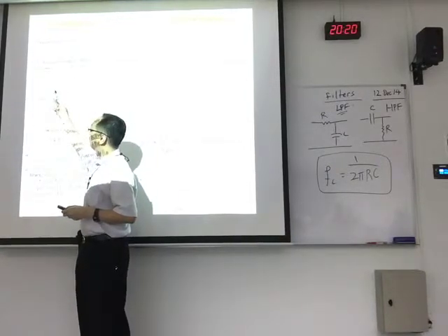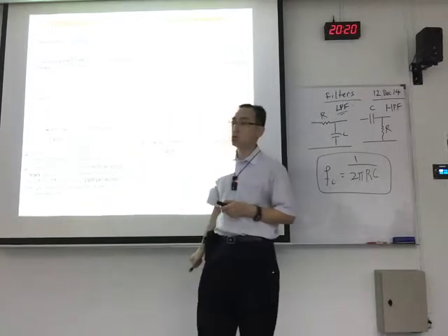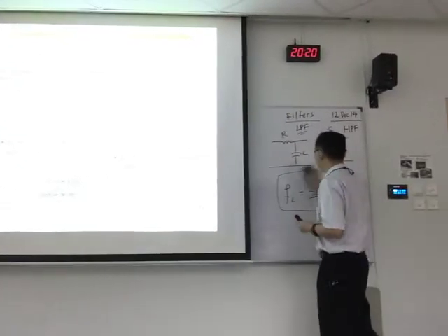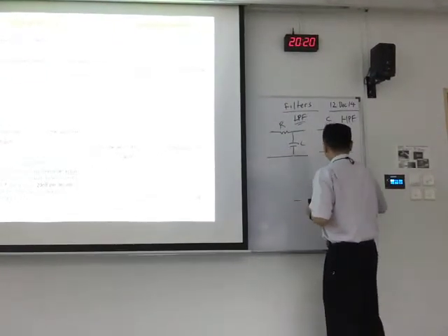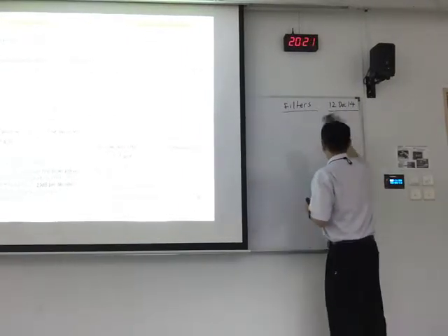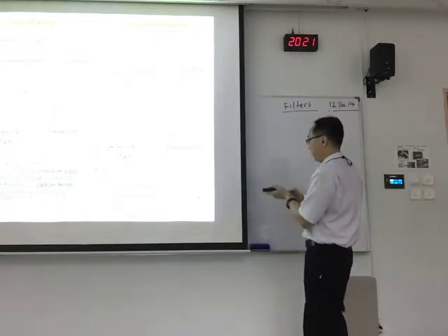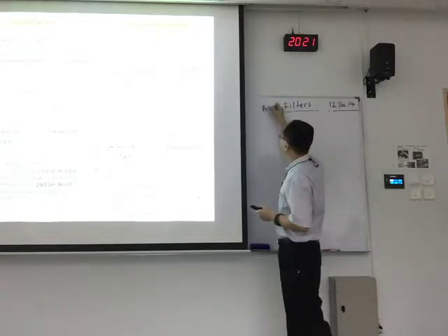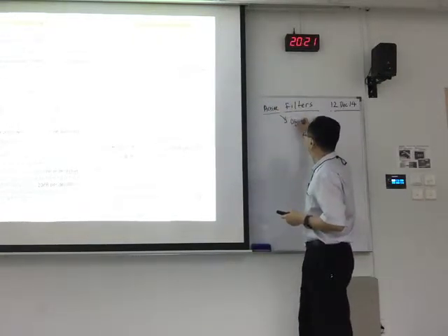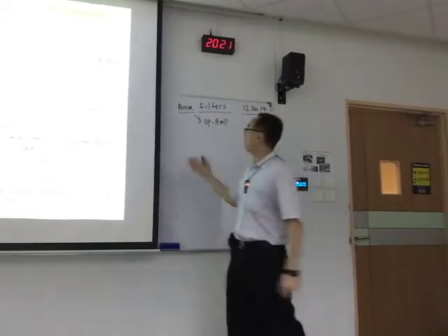Now what is this? Do you know? Op-amp. It's a voltage follower. So let me erase this part here. Okay, so what you do now is to make the filter active. Why do I say active? The main reason why I say active filter now is you need a supply. Yes, correct. It's active because now I use an op-amp, and we know that if you use an op-amp, you need supply. Therefore, it's active.